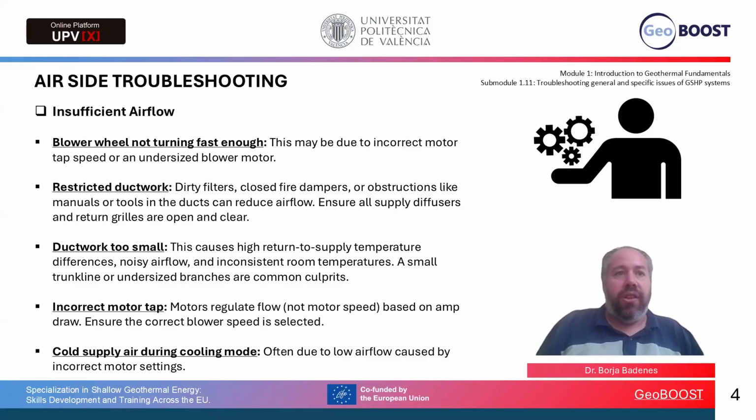3. The duct size. Too small ducts cause big temperature difference, noise, and uneven rooms. 4. The motor tap. Motor control airflow by the amp draw. Make sure the correct setting is used. And finally, cold supply air in the cooling mode often means low airflow. Check the motor setting first.